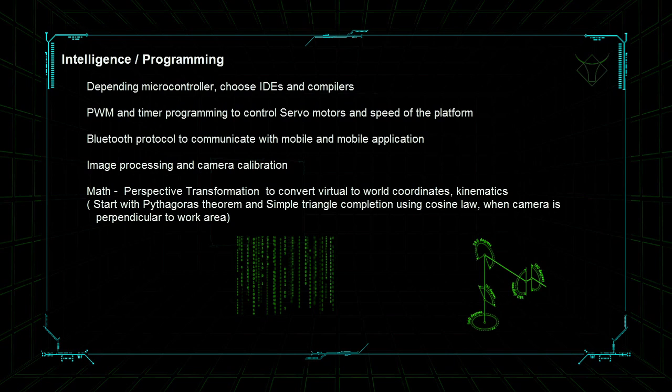We should also understand that a servo motor is controlled through PWM, PWM being pulse width modulation. The servo understands the width of the pulse we have generated, the positive pulse. So depending on the positive pulse, it turns its shaft to an angle. So a servo basically runs from 0 to 180 degrees. The pulse corresponding to 0 degrees is 1 millisecond, and for 2 milliseconds the servo will rotate its shaft to 180 degrees. Regarding this PWM, I'll be covering it in a different video.